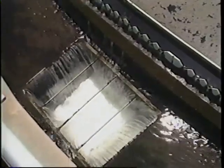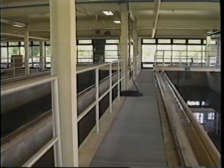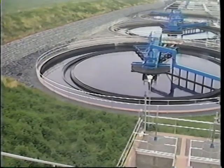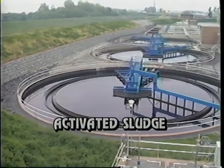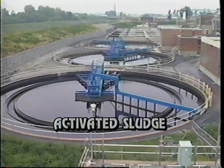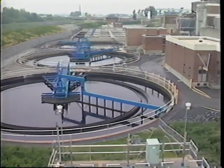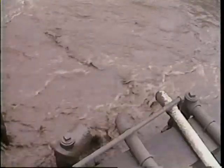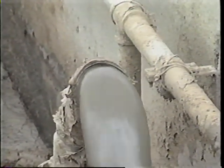The effluent from the aeration tank is called mixed liquor, and it is piped to a secondary clarifier where the feeding organisms will settle to the bottom while the clear water flows over the top of the effluent weirs and travels to the disinfection facility or on for tertiary treatment. The settled organisms in the secondary clarifier are known as activated sludge. A proportion of activated sludge is then pumped into the aeration tank, so the feeding organisms can be reintroduced, while the remainder is pumped to solids handling facilities.